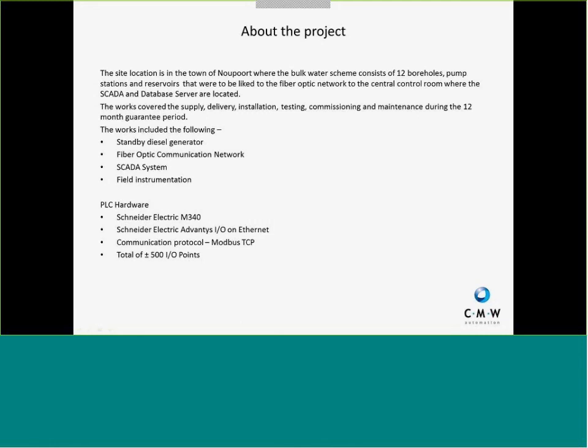The project originally did not start with the Schneider Electric PLC, and currently is now a Schneider Electric M340 PLC with Schneider Electric Advantys I/O on Ethernet, and the communication protocol is Modbus TCP. We have approximately 500 real I/O points, apart from set points, etc., for the whole project.